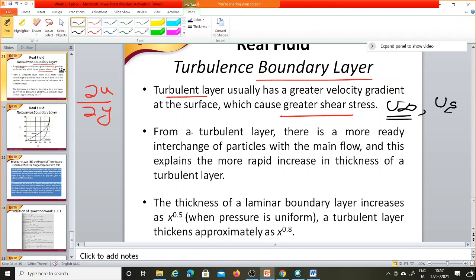So I just continue. In case of turbulent flow, we have the greater shear stress. It means we have the greater resistance. Similarly, when we have a ship sailing, initially we need to overcome the frictional resistance. So it depends on the turbulence or vorticity. It's very important. You will learn about vortex and turbulence and friction resistance in the resistance and propulsion part. It's a different course, but I will explain why we need to know these things.